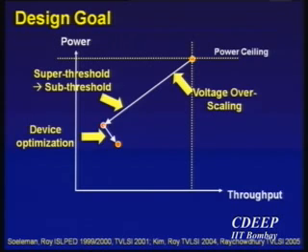But before that, if I'm always going to be operating in the subthreshold region, the question is, should I really use the same kind of devices that I would otherwise use for superthreshold operation? The answer is no. You can make device optimizations. I'm not going to talk about those here, but based on some of the device optimizations that we did, Lincoln Labs fabricated some interesting devices, and we are going to be fabricating some of those as a part of this Lincoln Lab run, but those are suited for subthreshold operations. Provided you're going to be running it only in the subthreshold region. If you want to go back and forth, no, then you can't do it.